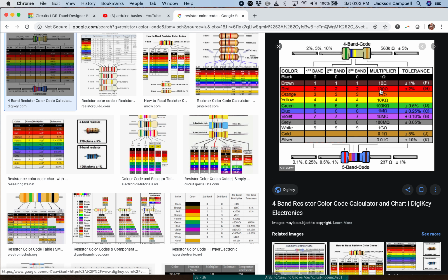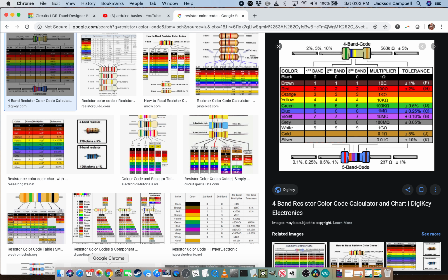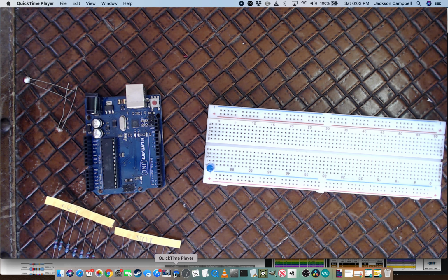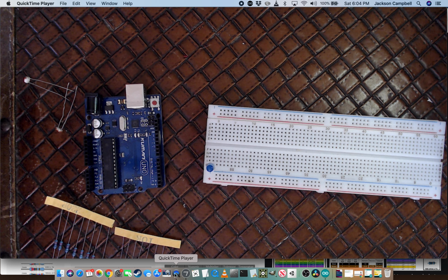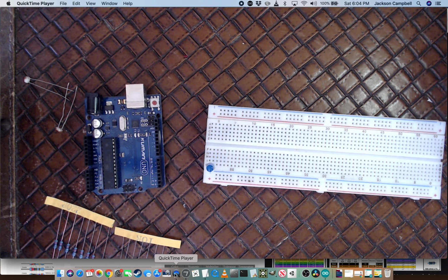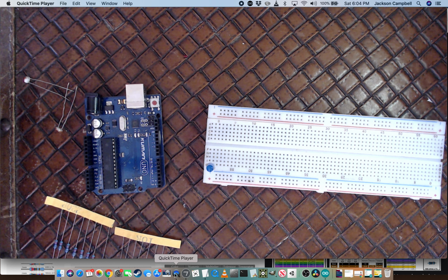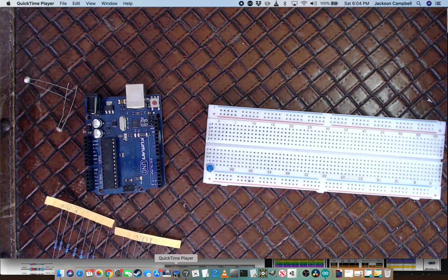So, you know, look at your resistors if they're not labeled, and if your kit has resistors that aren't labeled, then figure out what they are and write it on the paper, because it's way easier to do that than to try to look at every single resistor. But if you get them mixed up, or you're dealing with components you've already pulled out of the paper, then that's how you can figure out what it is. So this is a red, red, black, brown, which is a 220.